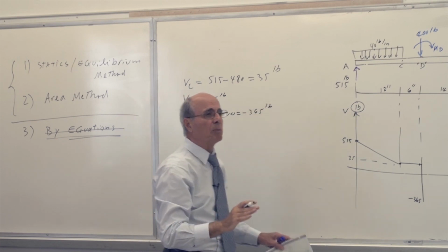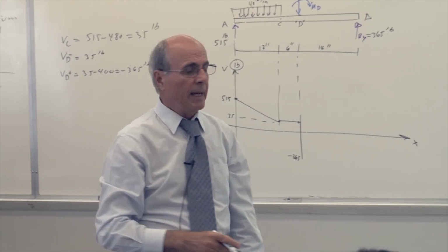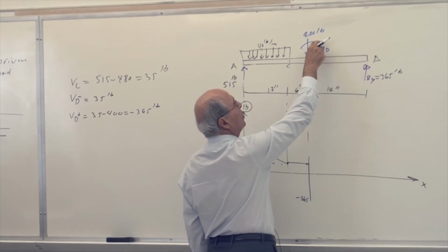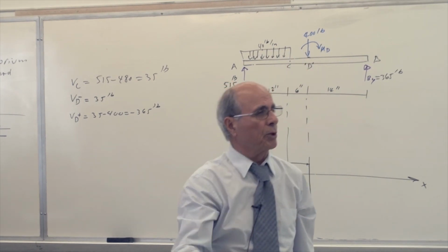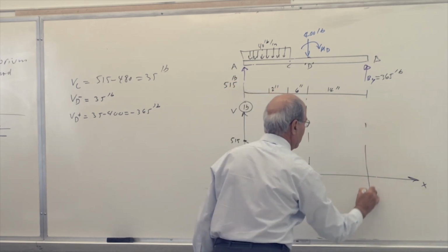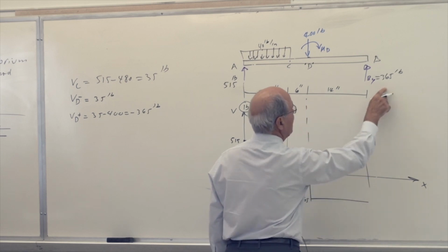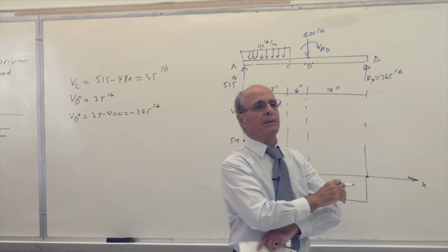We are just doing this by inspection. We are not using any formula or any equation. And you end up at F. So what happened after that? Notice moment does not change your shear. The shear is about forces only. Is that correct or not? Then nothing happens until point B, and at B I have to go up 600, so I end up back at 0.